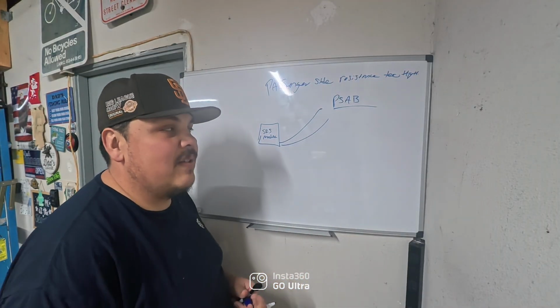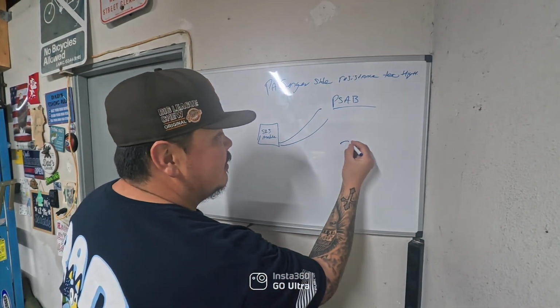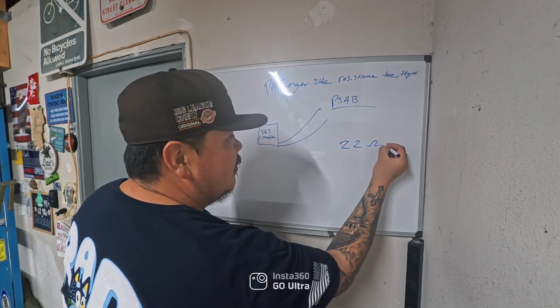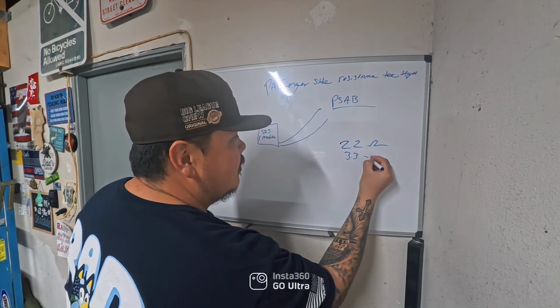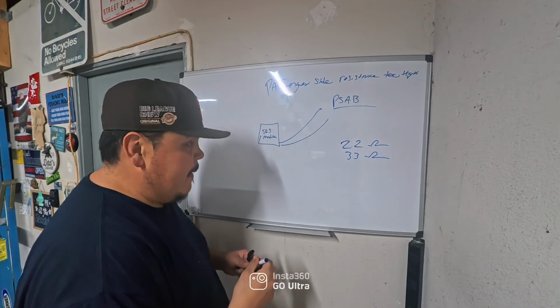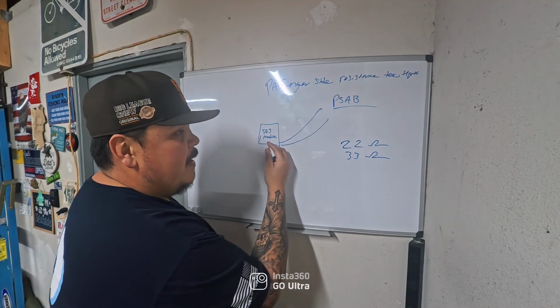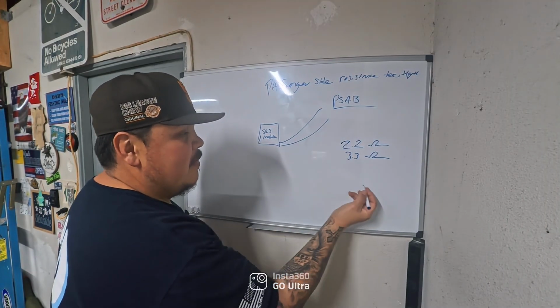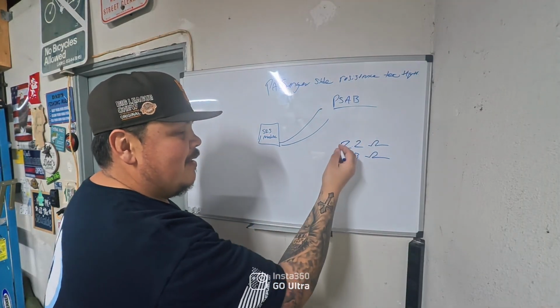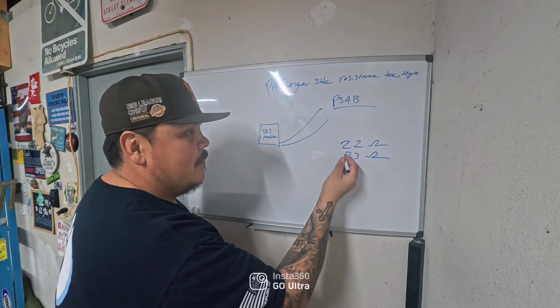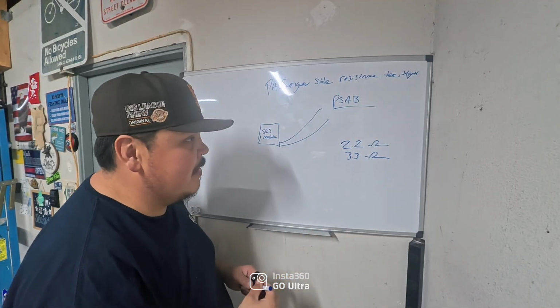Common resistances for airbag systems are 2.2 ohms and 3.3 ohms. The airbag module is looking at every component on its circuit, and they have a certain resistance value. That's the way it detects the code.